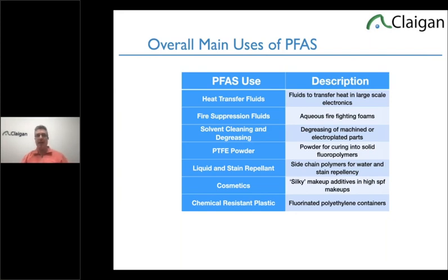Where a lot of companies will be impacted by changing regulation on PFAS is the machines that do the degreasing of their machine parts are all optimized with very specific, often a 3M material, PFAS. When they switch to an alternative one, the machine won't be as optimized in degreasing, and you're more likely to have quality problems. And it's because the degreasing machine is very much optimized to whatever PFAS is used.